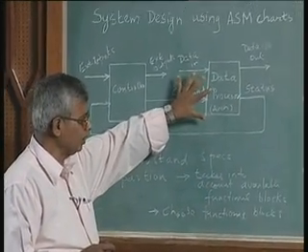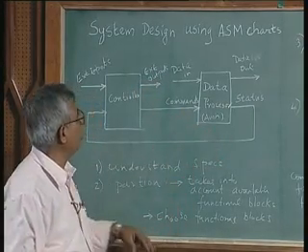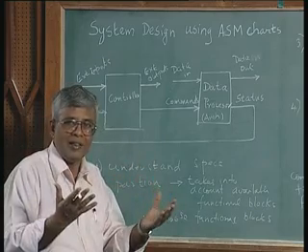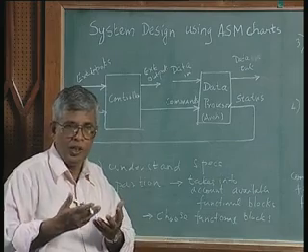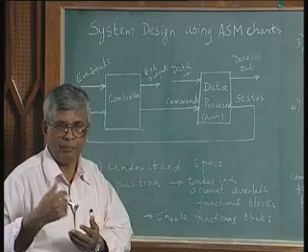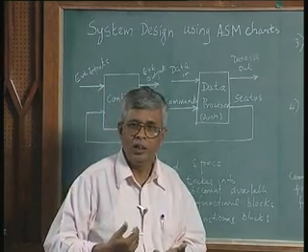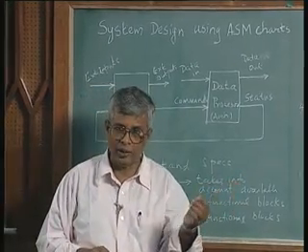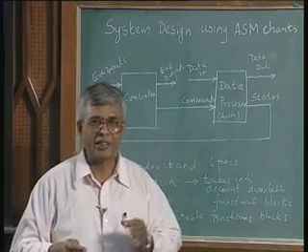We are given a problem at a global level or top level, that is why it is called top down design. At the top level the problem is given, and you try to understand what is required to be done, and whether there are any functional blocks which can do that job. If the functional blocks are available off the shelf, do not try to design them, get them. It can be in hardware form, it can be in Verilog. When I say functional block is off the shelf, it does not mean that you have to go and get it from a shelf. It is a way of saying it is available.